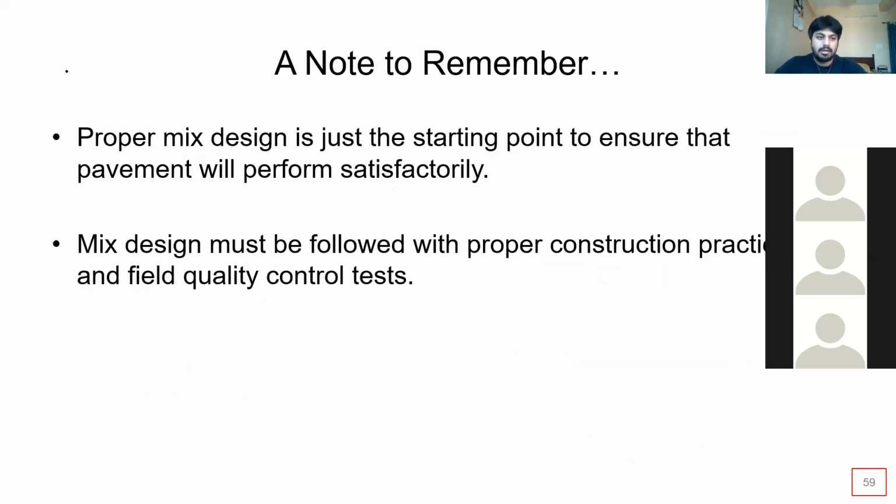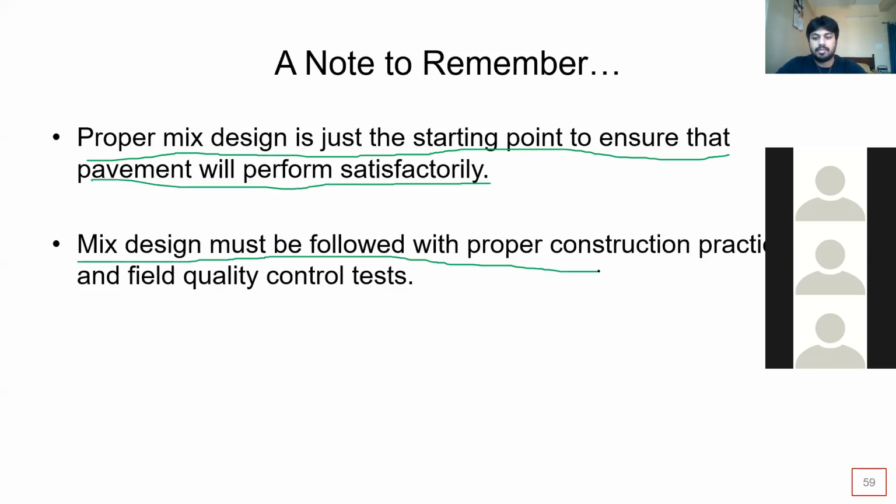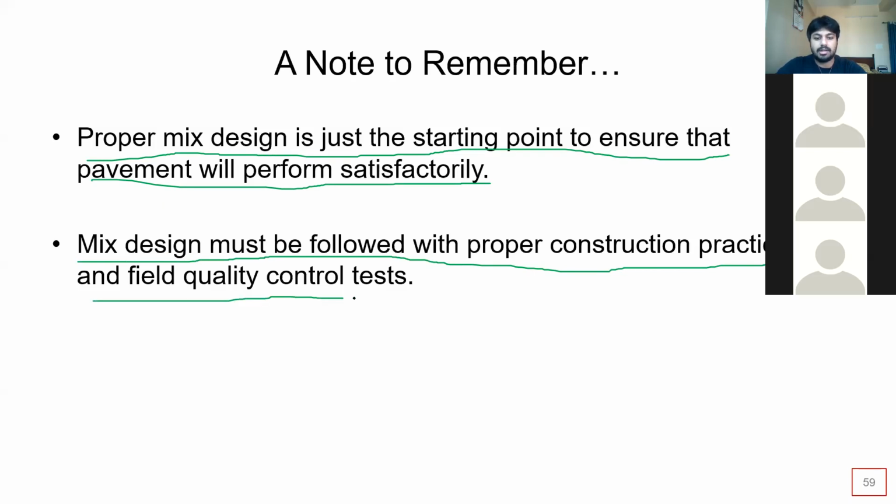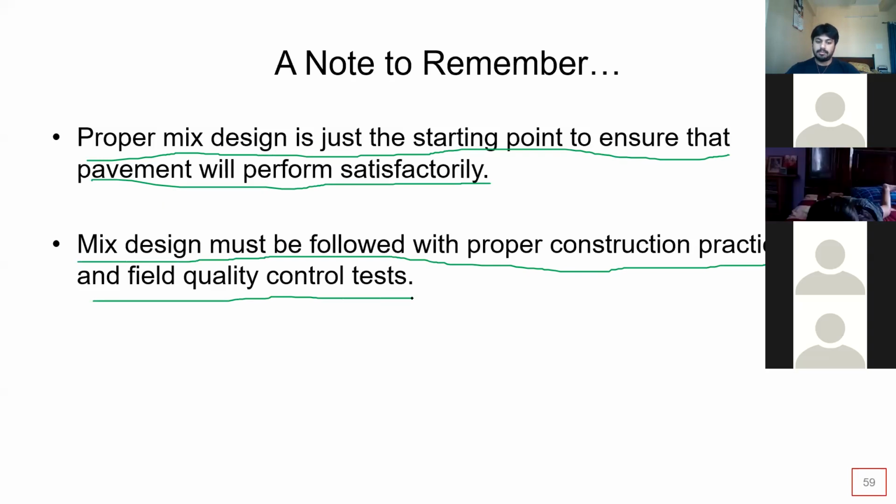Okay. So, not to forget, proper mix design is just the starting point to ensure that pavement will perform satisfactorily. Mix design must be followed with proper construction practice and field quality control tests. So mix design, as an engineer, as a designer, you have done the mix design, but if it is not followed according to the test protocols, then it is of no use.